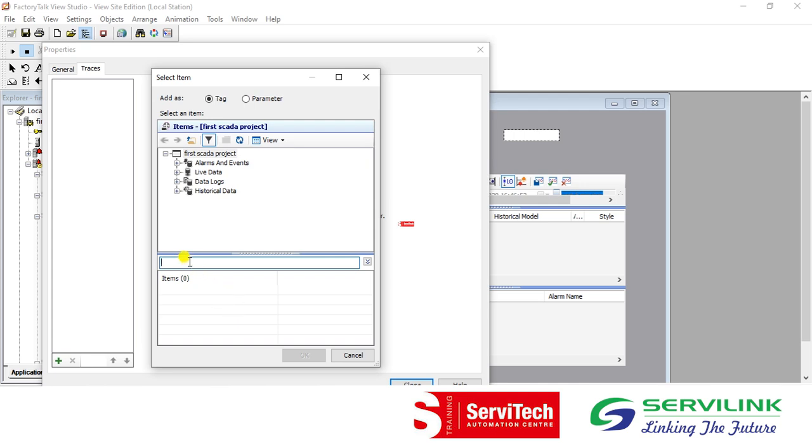You can write the name of that particular address directly, or you can go to Live Data and select our SCADA folder that we are communicating with through the SCADA software, and select this integer address. In this integer address you can find your items at the bottom by double clicking on this integer.